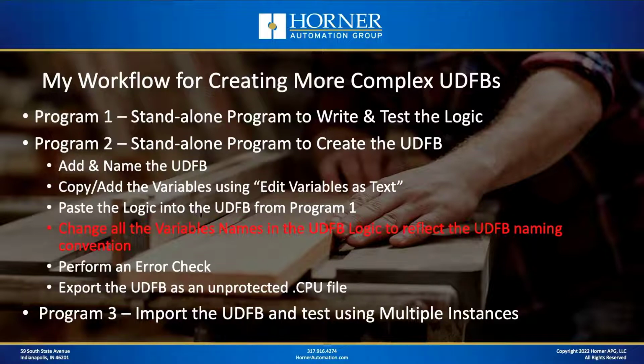Now, after I've done that pasting, all the variable names in the logic need to be replaced with variable names that are appropriate for the user-defined function block. And in a minute, I'm going to show you a slide which kind of illustrates the differences between variable names in your main loop or in a subroutine and variable names in a UDFB. So once you've gone through and you've set all the variable names to appropriate, then you're going to perform an error check, because there's plenty of room for errors at this stage. So you want to make sure that you've eliminated those. So you do the error check just to make sure you didn't make any mistakes.